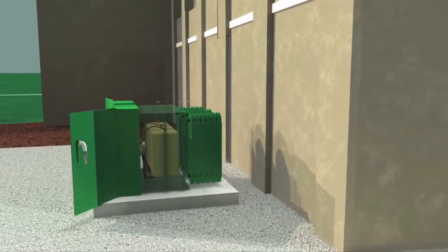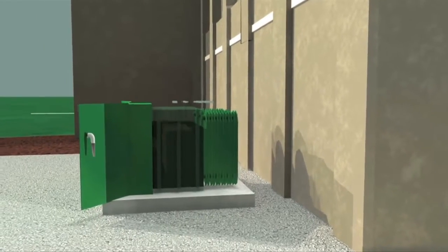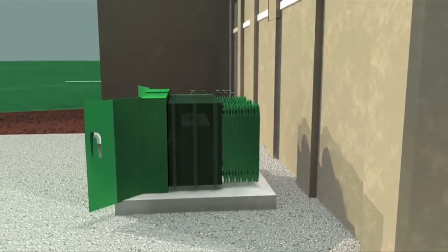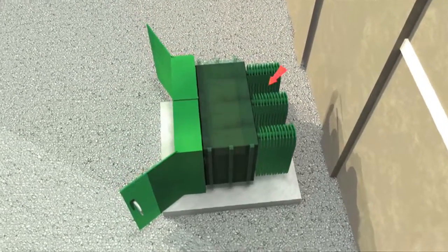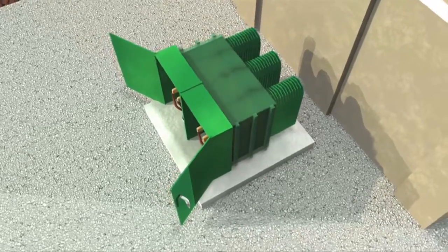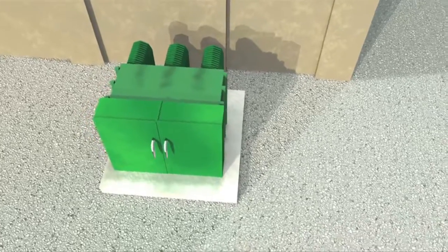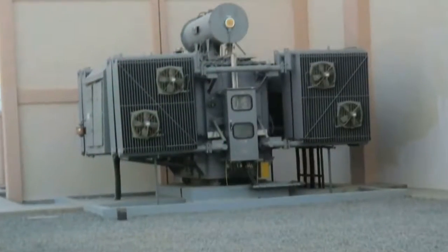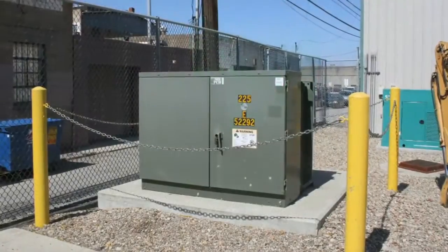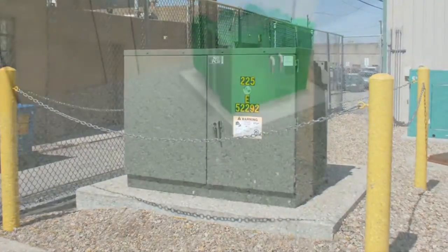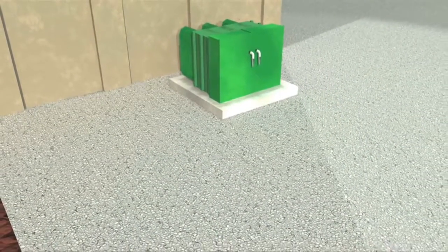The oil in an oil transformer is used for cooling. The core is filled with non-conductive oil. In most cases, mineral oil is used. Traveling through fins cools this oil, which utilizes the conduction process. Usually there are no pumps in smaller oil transformers. In addition to fins, some larger oil transformers will have exterior fans with thermostats that blow additional cool air over the fins. Oil transformers are placed on a concrete pad and almost always located outside the facility. This is in part due to a high fire risk.